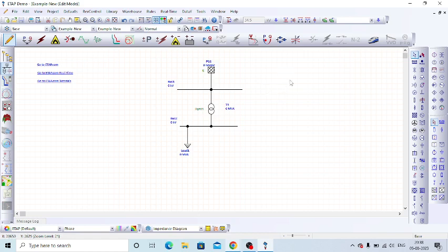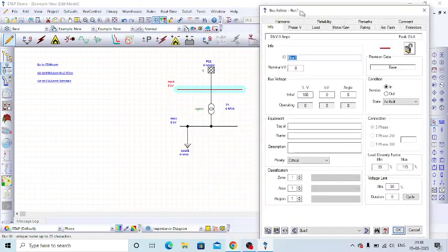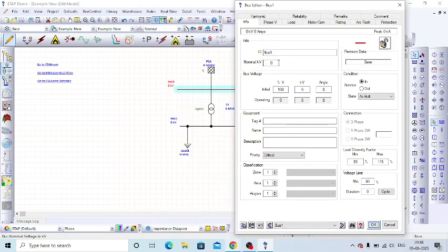Then after that, I have made the two bus element. In our last class we saw the two bus system. In the two bus system, we saw the bus, transformer, static load, motor load, capacitor bank. So I will just rebuild that one. First we have to enter the bus element. In the bus element we have to enter the ID and the voltage. Now we consider the voltage as 230 kV.